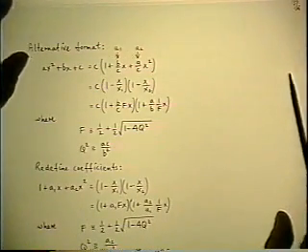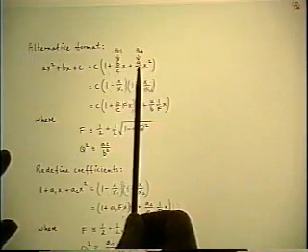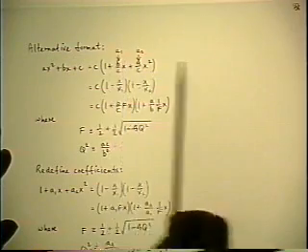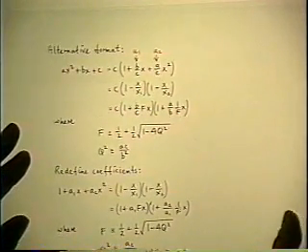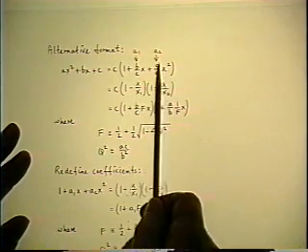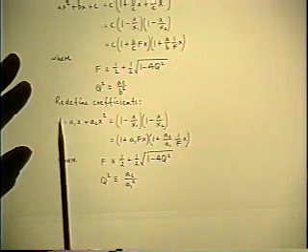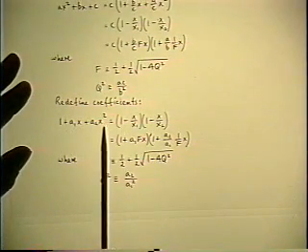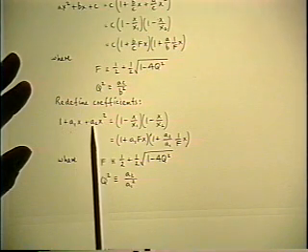And again, picking up the point that was brought up earlier, there are only two independent parameters that determine the roots. So you can rewrite them as a1 and a2. So if I redefine them as I have down here, here's the quadratic with ascending powers of x, or complex frequency, with appropriate coefficients in terms of circuit elements.